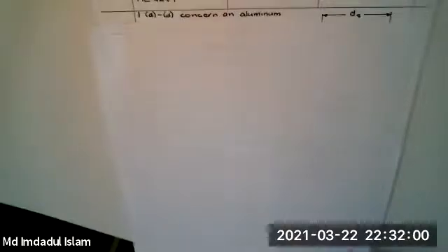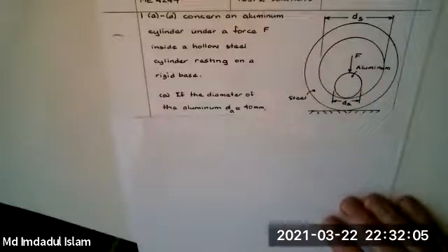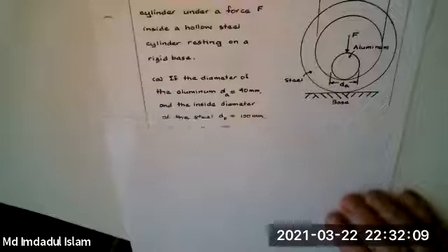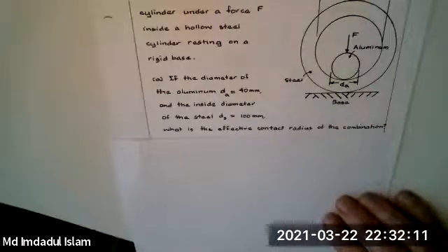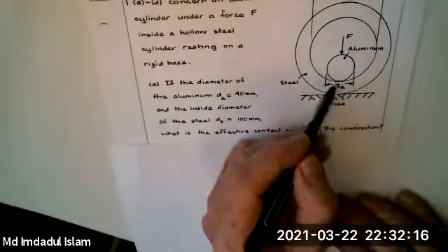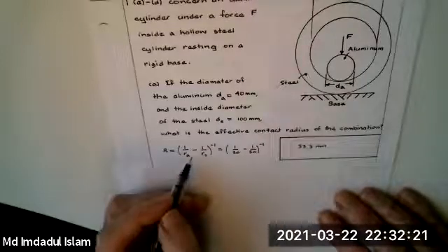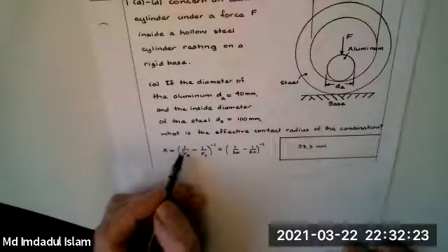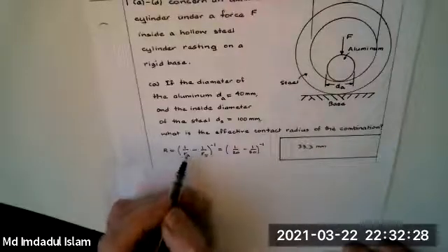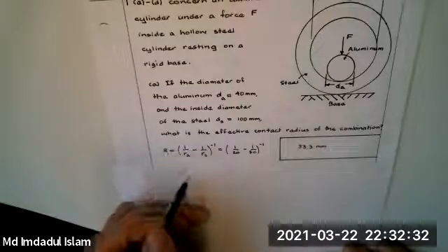All right, let me start through test 2. The first 4 problems are about contact stresses, 1-point problems. When you have something like this, then the steel is wrapping around the aluminum and expanding the contact radius. What you're going to do is you subtract: you have 1 upon RA for the aluminum minus 1 upon RS, to the minus 1. When you put the minus sign in here, this makes it smaller. When you take the reciprocal, it makes it bigger.